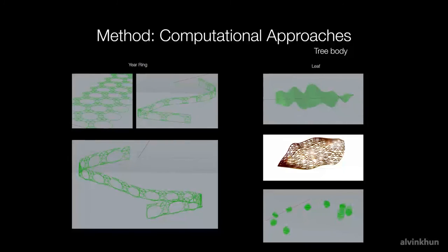Then I try to map the leaf geometry around the bracelet, but the custom geometry does not have a creation point, and the geo node has a geometry input and geometry output. For anything that I want to move somewhere, I have to use a move node and create a vector. So I use a vector 2-point node to find a vector between the center point and all the other points. After the geo is mapped to the bracelet points, I randomly rotate them.